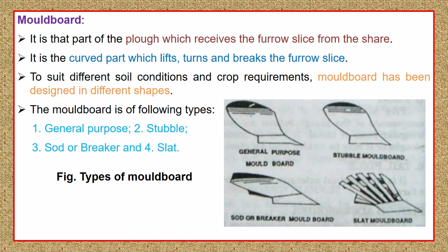So general ploughing, irrespective of any special type of field requirement, may be used. General purpose ploughs have features like a wide moldboard, and its curvature, that is the curved surface, is gradual, not rapid or abrupt, and therefore they give a thorough pulverization.